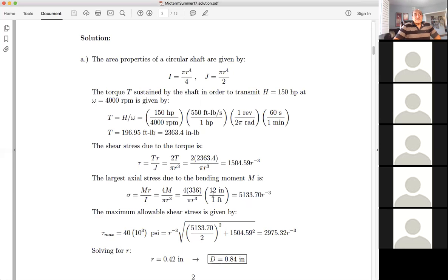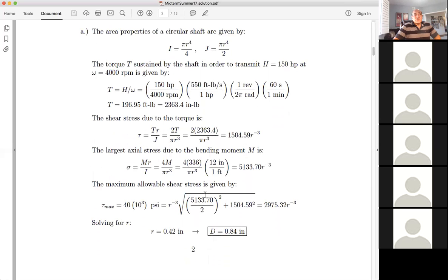And then we use the Mohr circle analysis. And in this case, we got trained so much that the Mohr circle, if we want to find the radius, is the square root of sigma x minus sigma y over 2 squared plus tau squared.